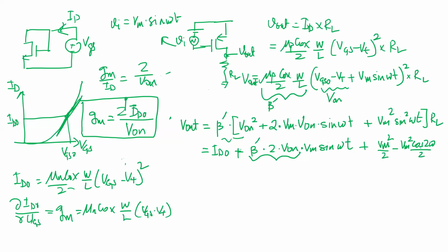So you get the DC current and the sine wave term, Gm times that. And this is all you wanted, right? You had the DC and you wanted to amplify that audio signal, but you have this term now. No, it's not noise distortion. It is dependent on the signal, because this is related to the signal, cos 2 omega t. But it's twice the frequency now. That's the harmonic, right?